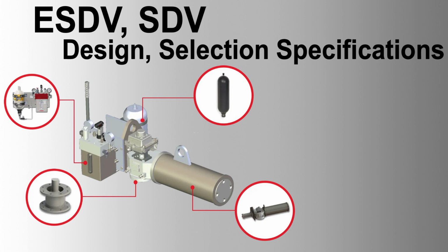Partial stroke test device, PST. Requirement: field-proven, SIL 3 certified, connected to PCS. Diagnostics: internal checks, spurious trip protection. Operation: 4 to 20 mA DC control signal from PCS. Features: warning of maintenance operator, load factor, air leakage, breakaway pressure, fault detection, dynamic valve torque, and valve stuck alert.